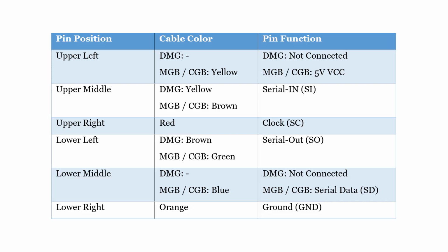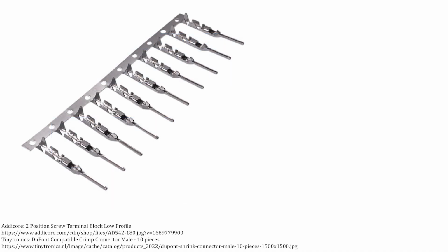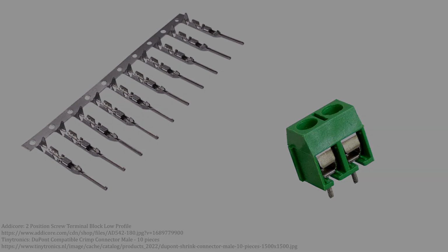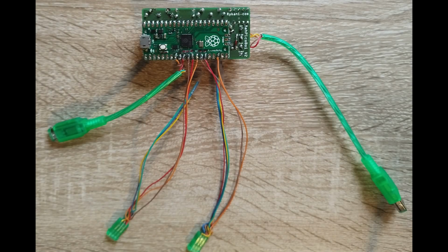Now that you've got the appropriate internal cables at hand, it's time to hook them up to the Raspberry Pi Pico of our MahPicoBoi setup. Depending on the version of MahPicoBoi you own, there are several different methods available to you. If you've built a MahPicoBoi on a breadboard, you could use either several DuPont connectors or a 2.54 or 5.08mm screw terminal. If you own a pre-built MahPicoBoi, you'll most likely just want to solder the exposed copper parts of the wires, just like I did.